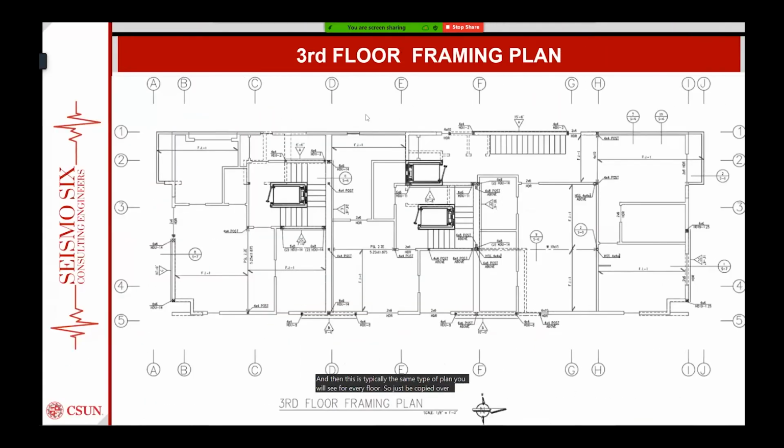So here's the third floor framing plan. There wasn't really anything too hard about this. We just had to section off some of the beams because we didn't want the joist to be too long. For example, between D and E, FJ1, there's a PSL running orthogonally to it, so we wouldn't have to extend it all the way to the header above.